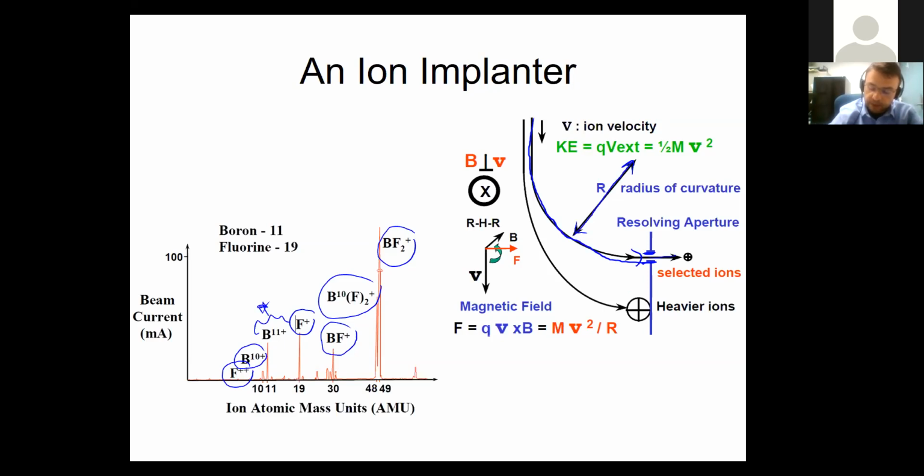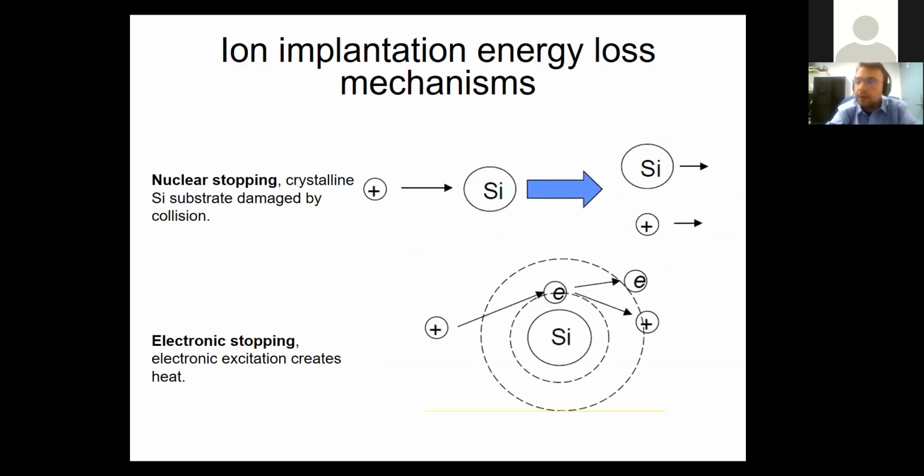And the other ones, the heavier ones, their mass will increase. See, in this simple equation, it's the Lorentz force equating to the centrifugal force, if you're familiar. If not, that's not too critical, but what's happening is the R, if you take it out to the other side, is proportional to the mass. So the radius, the trajectory can be predicted. And you can filter out these heavier ions. You can make sure that they won't infiltrate into your silicon surface.